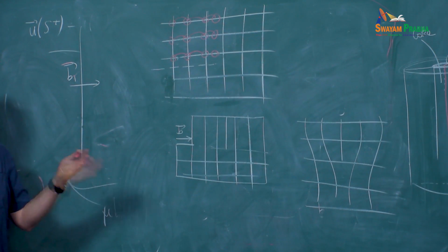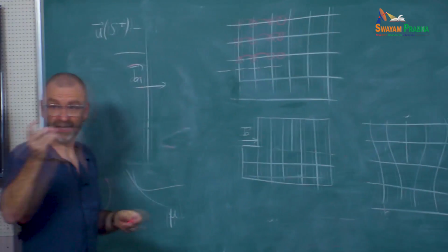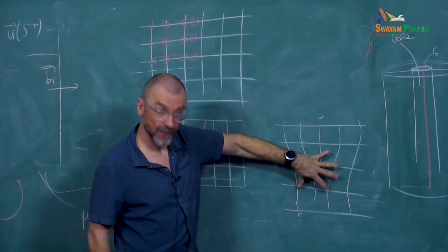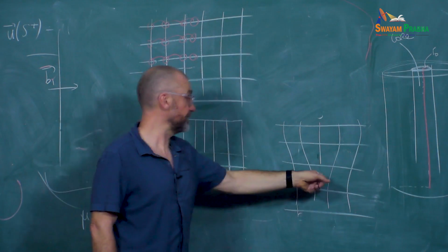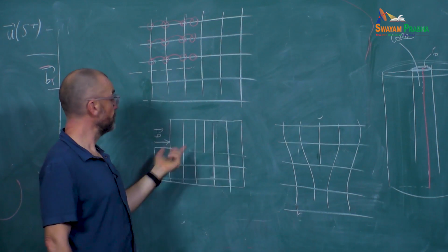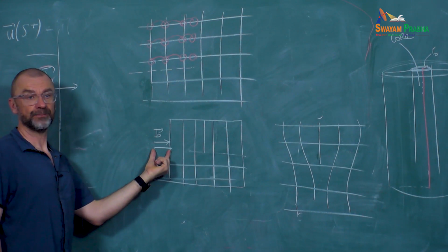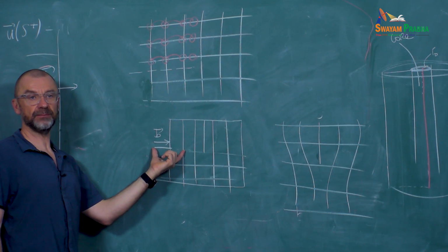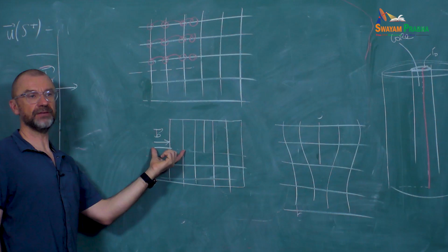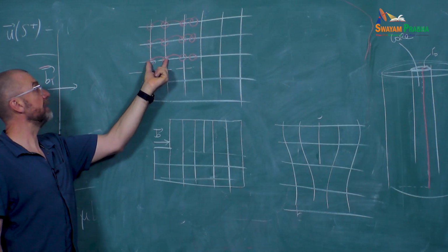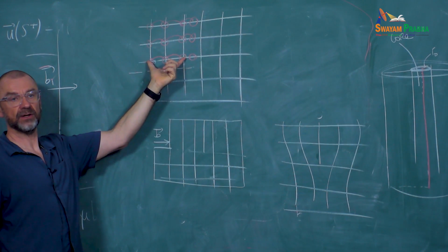Yes, so that's an edge dislocation, and as you all know, it corresponds to an extra half plane that stops in the crystal, and the dislocation is perpendicular to the board. And the smallest vector I can use to create the dislocation is this one. Now, could I use two Burgers vectors to do the same? Or what would happen if I use two Burgers vectors? Two interatomic distances, I mean. Instead of shearing by one distance, if I do it with two distances, what is going to happen?